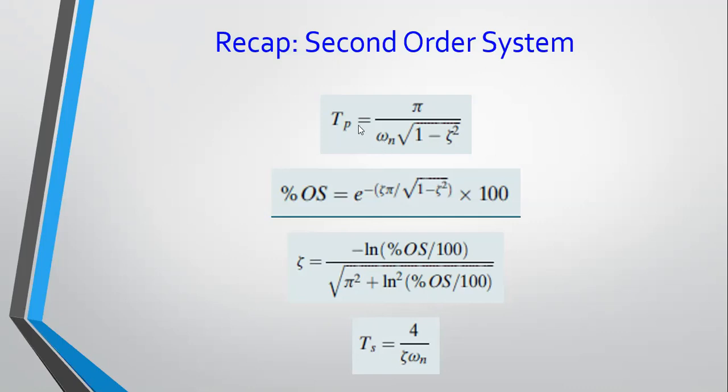So these two parameters, we're going to look at these two specifically. This one as well is related to your damping ratio, as you can see here. Once you set your damping ratio line, you can very well find your percentage overshoot, because percentage overshoot is not dependent on the natural frequency, whereas these two are actually dependent.